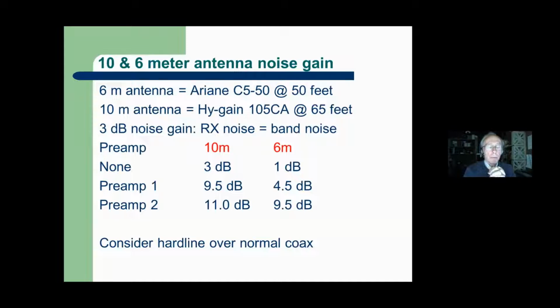So what we do is you can listen to the noise coming out of the radio. I'll of course put a meter on it so I can measure it in dB, but you can do it by ear. So then you switch between your dummy load and your antenna with no signal tuned in, of course. And we really want band noise to go up significantly. So here's 3 examples for each band.